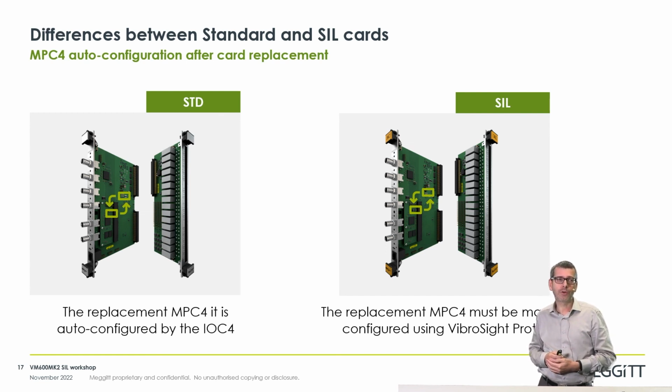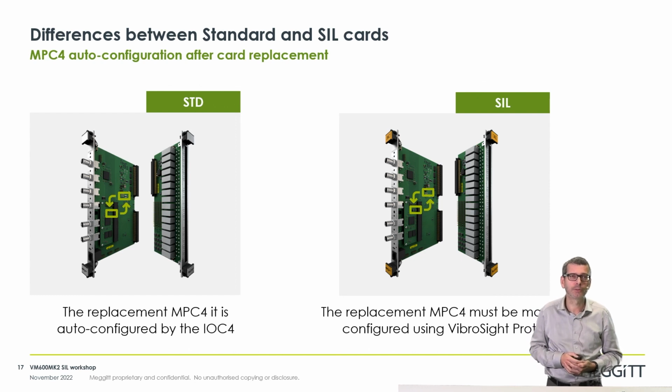So there is no software intervention required, no reconfiguration of the card. That is not allowed on the SIL card. That does not meet the SIL requirements. So in case of SIL, if the MPC4 has to be replaced, the card has to be reconfigured and the configuration has to be resigned using Vibro-Safe Protect.